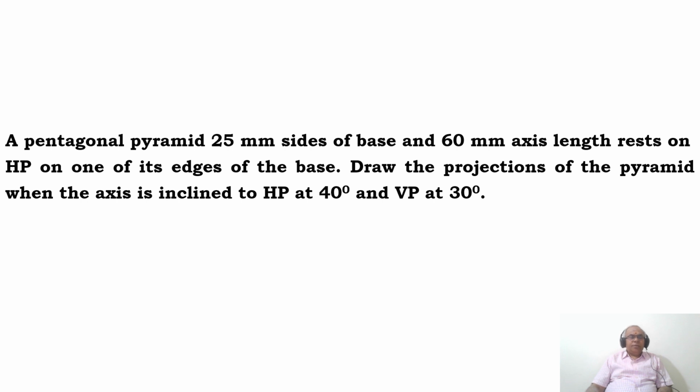Now, in this video, we are going to take up one more problem on projections of solids. How to analyze this problem and solve it by using the sketchbook. The problem reads as: a pentagonal pyramid, 25 mm sides of base and 60 mm axis length, rests on HP on one of its edges of the base. Draw the projections of the pyramid when the axis is inclined to HP at 40 degrees and VP at 30 degrees.